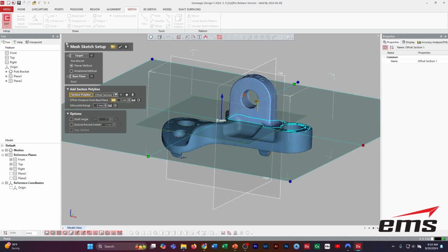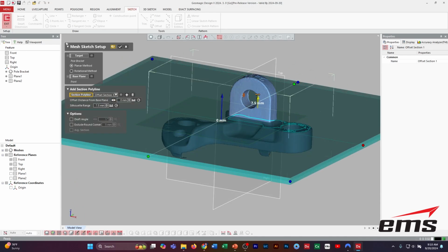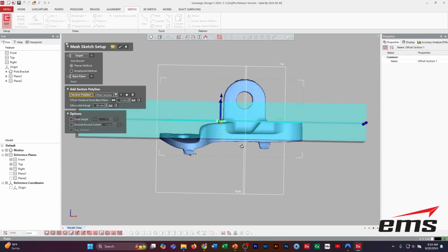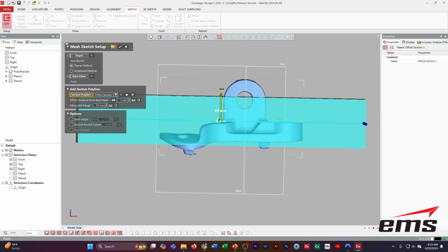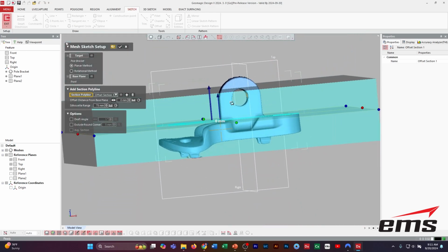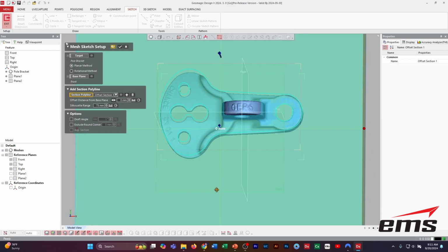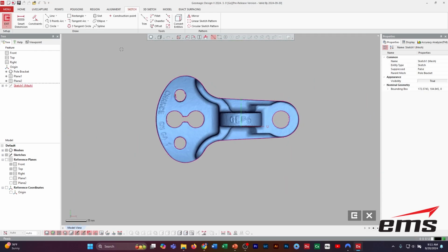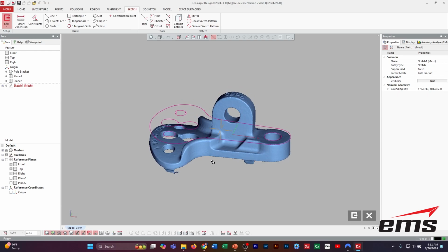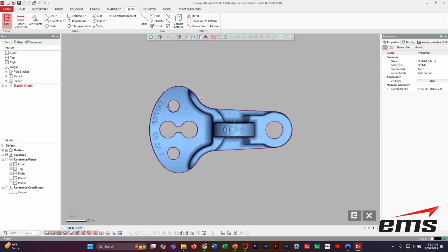And then over here, we've got another little arrow we can drag up, and this is called silhouette. Let me get in the side here. I'm going to drag that one up until the whole thing is encompassed. If you're familiar with a parting line in a mold, it just looks at the farthest out point on the scan data in this area that I've picked. So you can see what it's done. I'm going to hit OK. Now it's up on that plane, but again, I don't care where it is. So now I have this profile.